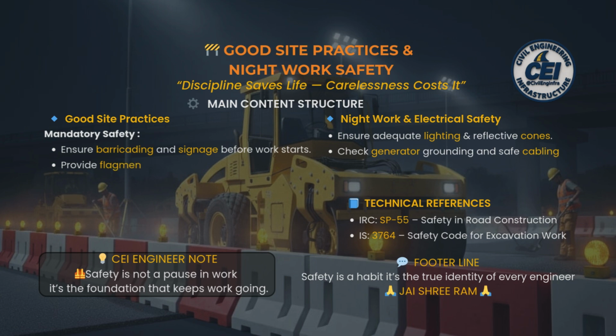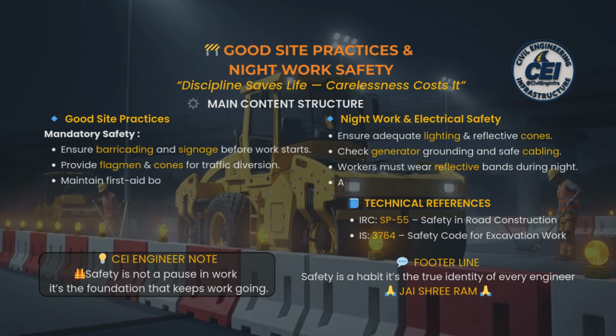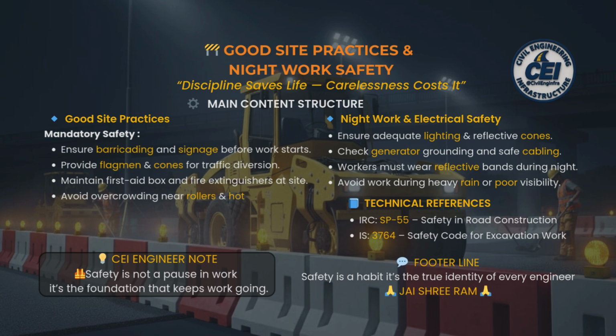Good site practices. Ensure barricading and signage before work. Provide flagmen and cones for diversion. Keep first aid box and fire extinguishers ready. Avoid crowding near rollers or hot mix. Conduct toolbox talk before every shift. Never stand behind a moving paver or roller. Night work and electrical safety. Ensure lighting and reflective cones.